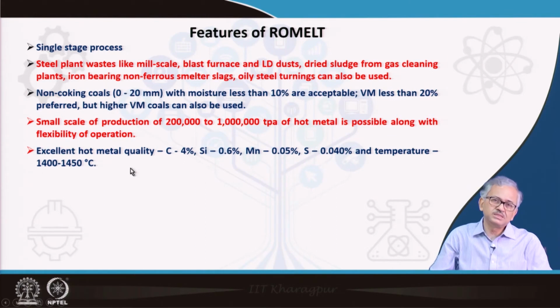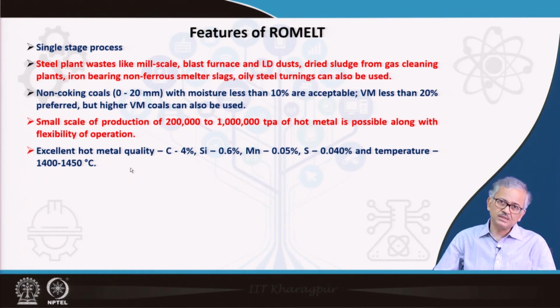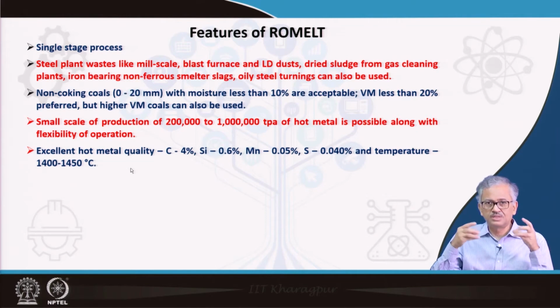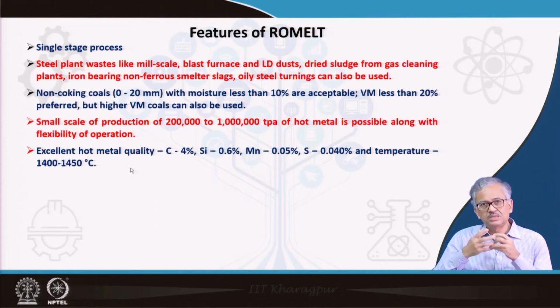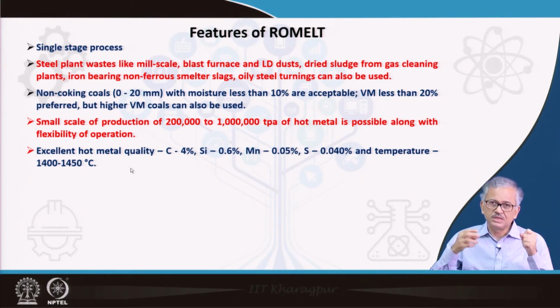And here in the single stage reactor, one thing is the slag that is generated. Basically you can find the emulsion forms in the upper part, and there some slag metal partitioning takes place because slag contains FeO. The FeO is oxidizing, so the slag becomes a little oxidizing there, and then it can partition some amount of the phosphorus and sulfur. That is why you can get a very low phosphorus also.